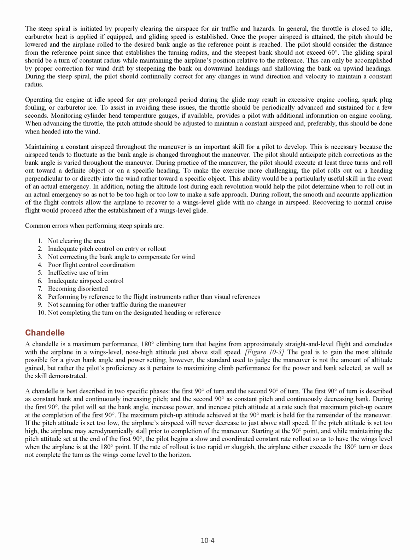However, the standard used to judge the maneuver is not the amount of altitude gained, but rather the pilot's proficiency as it pertains to maximizing climb performance for the power and bank selected, as well as the skill demonstrated. A chandelle is best described in 2 specific phases, the first 90 degrees of turn and the second 90 degrees of turn. The first 90 degrees of turn is described as constant bank and continuously increasing pitch, and the second 90 degrees is constant pitch and continuously decreasing bank.